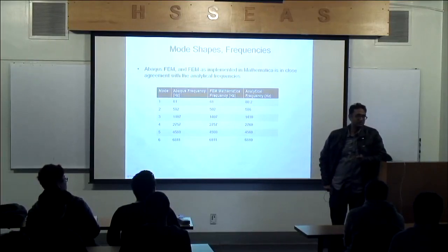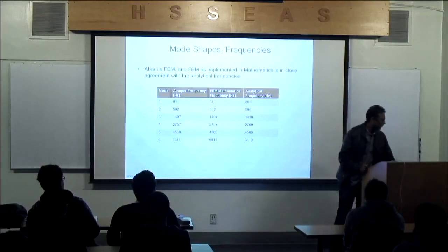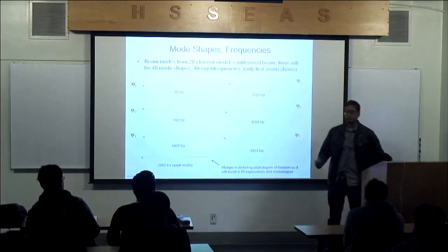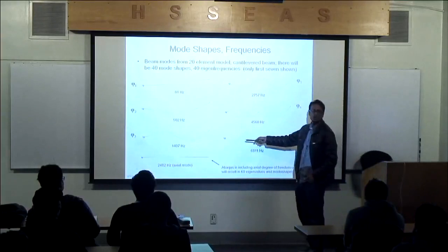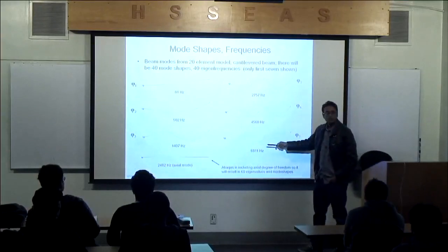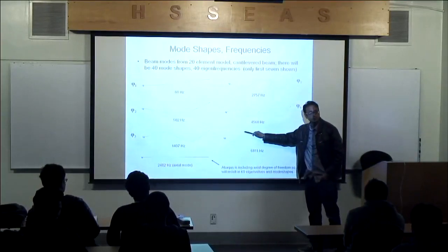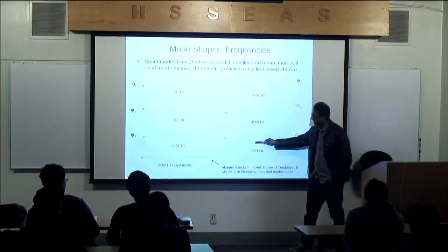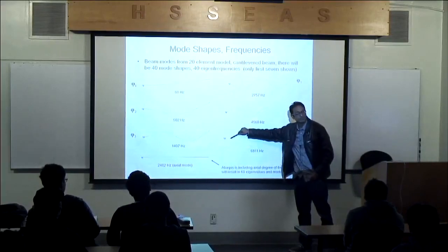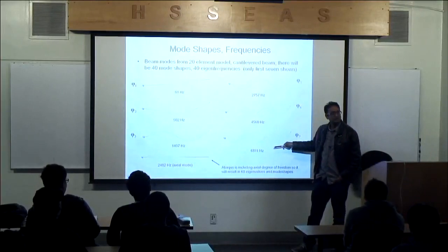You mentioned that there's going to be errors when you go further down the list. Why is that so? Well, for example, when I look at this, how many elements do I have here? 20 elements? The more bending I have, so the more frequency and bendings I have, my elements are going to perform poorly, right? Because they need to conform to that shape, and they can't.